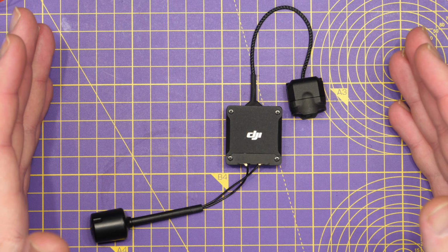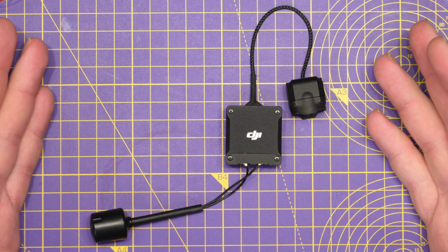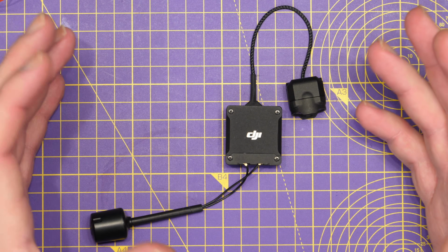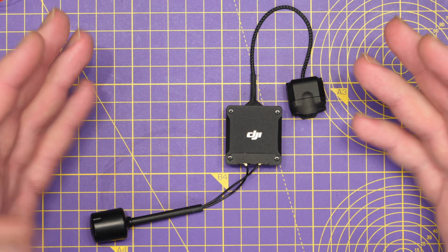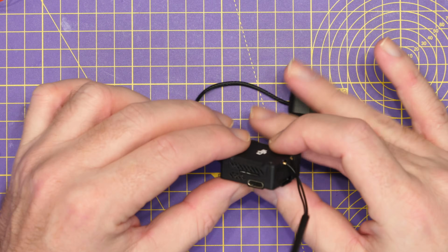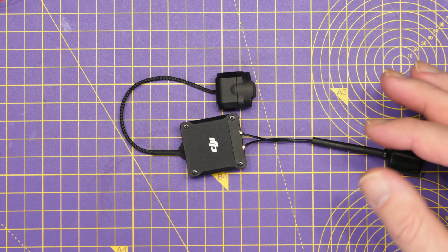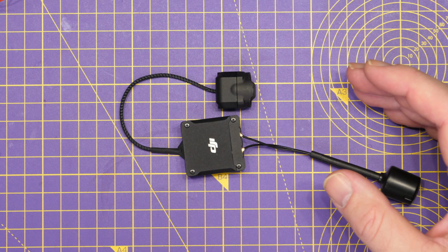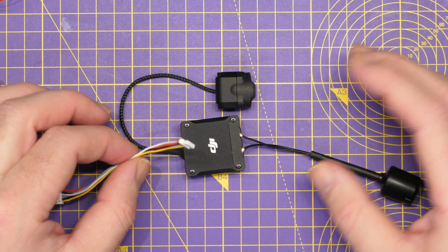With regards to power, there are some basic things you need to be aware of. The O3E unit will not work from USB. I have seen a few people question why they can't get their O3E unit to bind, and it turns out that they were actually trying to power it via that USB-C port on the side. The only way you are going to be able to get your E unit to power up is by using the power input for the main unit on its harness.